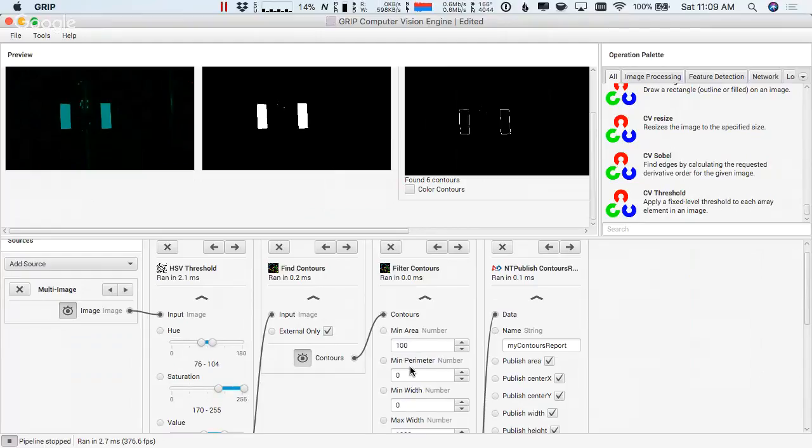Because these are pointing at 45 degrees instead of straight ahead, the force and the speed has to be multiplied by the square root of 2 over 2, so it's like 0.7. It's 7/10 of the pushing power and the speed of the same motors with conventional wheels.